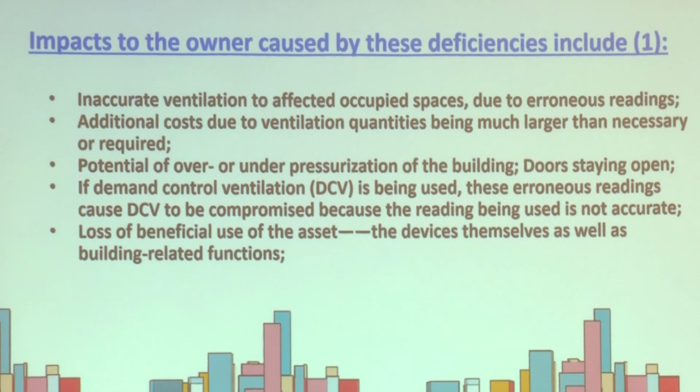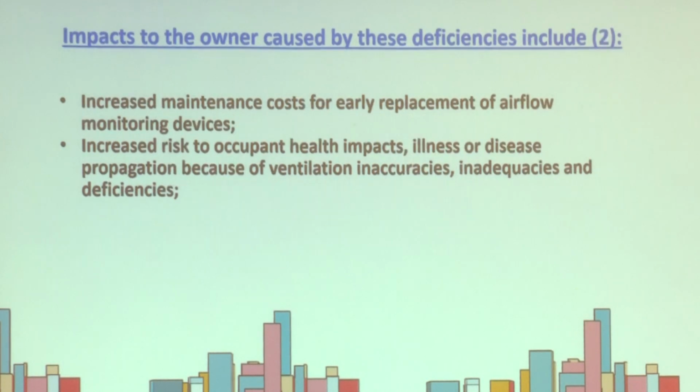So when I first got into this building, the complaints were so many, we couldn't help it. But we went through and we looked at all this and we said, we've got to fix it. So the first thing we did is we tried to clean them. But because they were in the airspace and they were so dirty, every time we tried to clean them, it didn't work. A couple, 2 or 3 of them did actually work after that, but the majority of them didn't. So again, the owner is having to have an increased maintenance cost because now they have to replace those airflow monitoring devices to make sure they work.